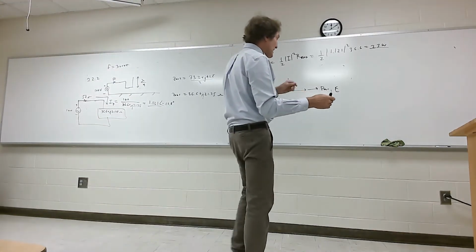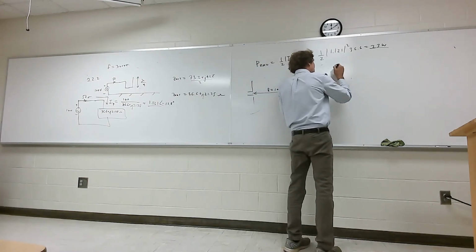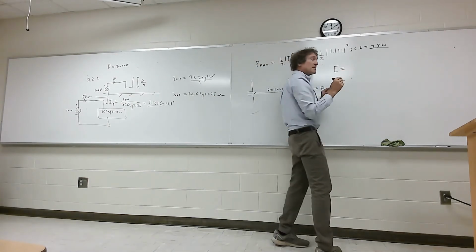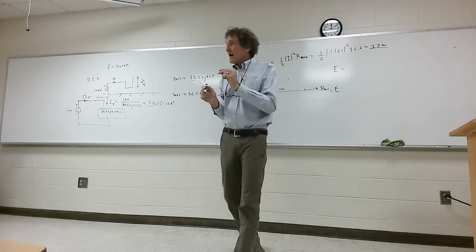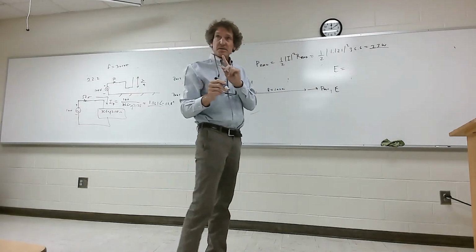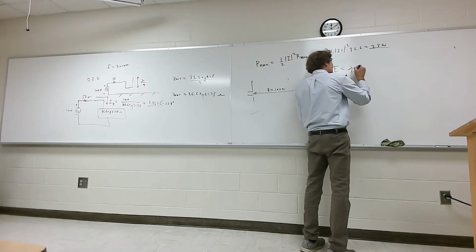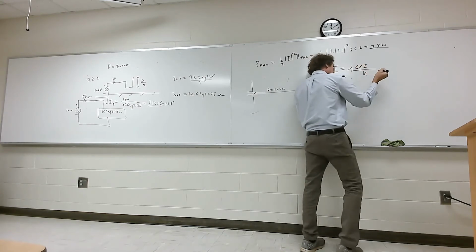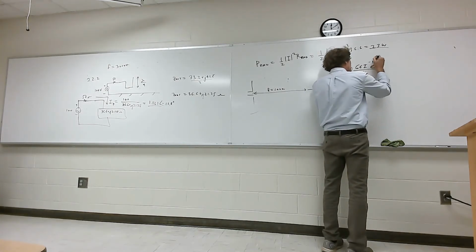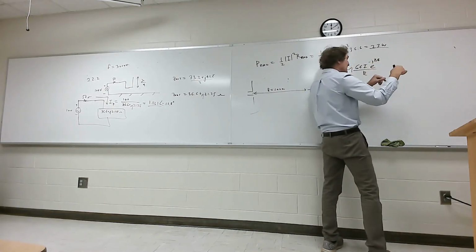We know that the electric field for a dipole, and it matters not if it's a monopole or half-wave dipole, once you know the current, this equation is the same. The electric field, if it's a half-wave, would be simply j times 60I over r. Then there's that e to the minus j beta r, which is a phase term we can forget about.